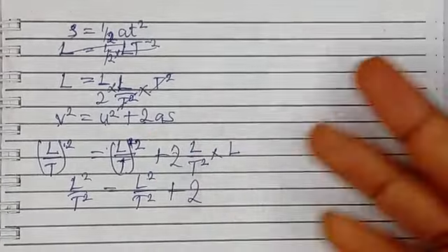Okay, we have that the power of wind moving at a speed v is used to turn a turbine of radius r and is given by P is equal to k, which is a constant. This is rho raised to power a, r raised to power b, and v raised to power c, where k is a constant of no dimension, and rho, this is not a small letter p, it is rho, a Greek letter, is density of air. Determine the values of a, b, and c using the method of dimensions.